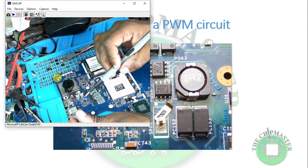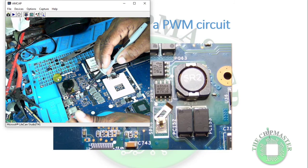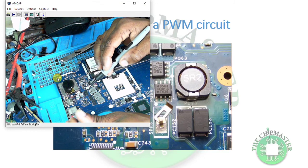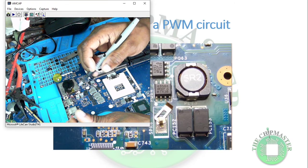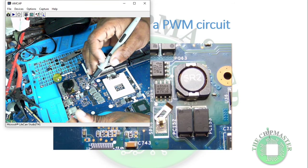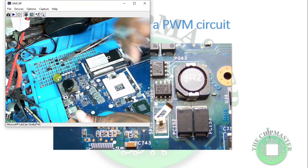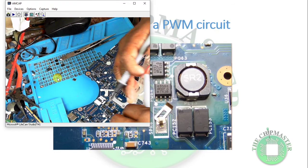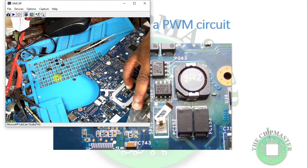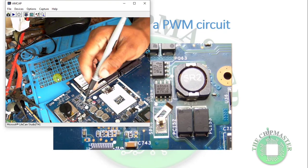What will happen is that there's normally a thermistor, which is an NTC, negative thermal coefficient resistor. When the temperature increases, its resistance decreases. So it measures the upper MOSFETs, which is on this side. Right, these are the ground MOSFETs. So for the upper MOSFET, there's a resistor that is connected close to it. On the back side, here it is. This is it.